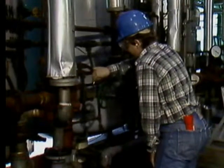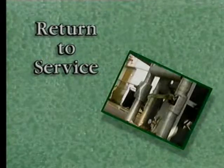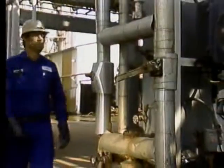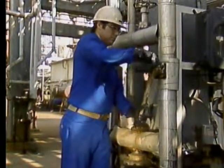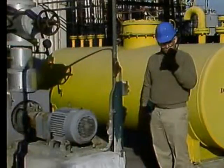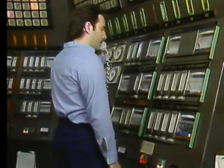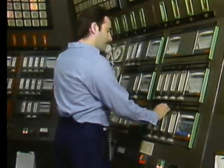After corrections have been made, the process can be returned to its normal operating condition. To return a process to normal operation, it may be necessary to reposition valves, switch the process back to automatic control, or adjust process variable set points to allow for a change in performance. If the problem has affected other processes or units in the plant, it's important to let them know that things are back to normal, so they can make adjustments at their end.